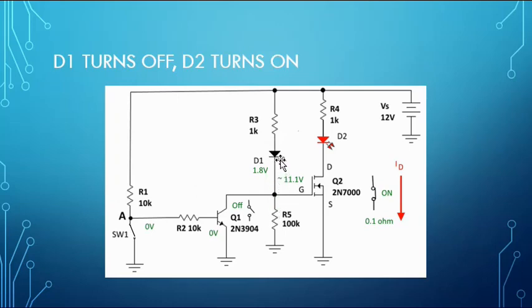Having said that, I have seen that some of the super bright LEDs will glow dimly even if we put a 100K resistor in series. So if we say 12 volts divided by 100K, we're looking at 1K is 12 milliamps, 10K is 1.2 milliamps, 100K is 120 microamps. So some of the super bright LEDs will even light up with 120 microamps in it.